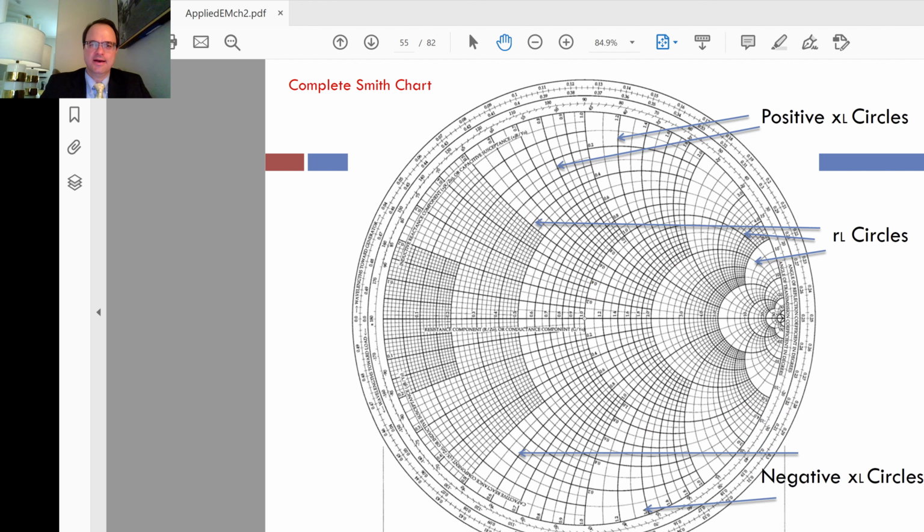And that's what the full Smith chart in all its glory now does. It puts both of those things on the same chart. The gamma sub R and the gamma sub I are naturally on this chart because that's what defines the X and Y axis in this complex plane. But onto this, we now put the family of RL circles and the family of XL circles.